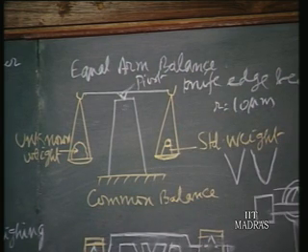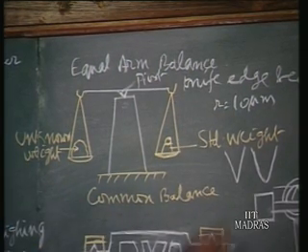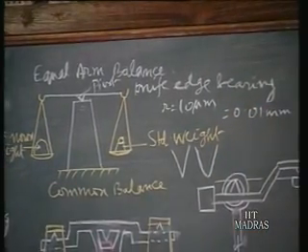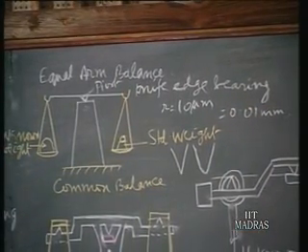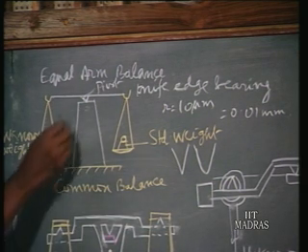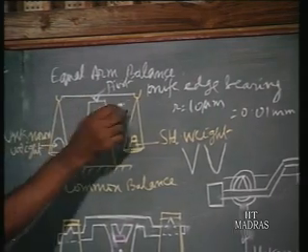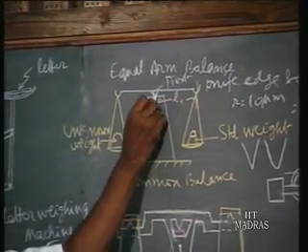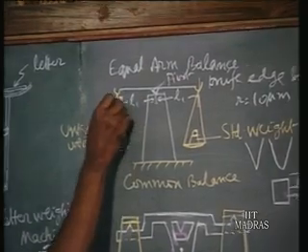So, you find the friction radius is 10 microns, which is equal to 0.01 millimeter. Hence, you will find the friction torque in such a knife edge bearing is very small. Hence, we have such accuracies. Here we have only one knife edge bearing, and the two ends are equal. This is L1, this is also L1 from the pivot. That is why it is called equal arm.